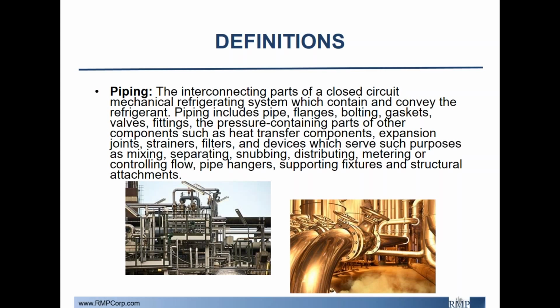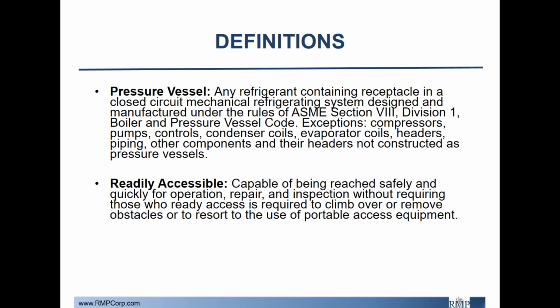Anything that can be used for a purpose of mixing, separating, snubbing, distributing, metering or controlling flow, pipe hangers, support fixtures, and structural attachments. So anything related to piping, valving, or interconnecting big pieces of equipment, by definition in the standard, is considered piping. Pressure vessels are exactly that.